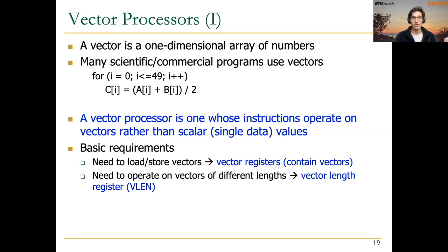And how are we going to operate on these 50 elements using 4 processing elements? We will go 4 by 4, right? So if we have 40, we will need 10 iterations, right? We will need 10 cycles to input all the operands to the processing elements and finish the execution sometime later.